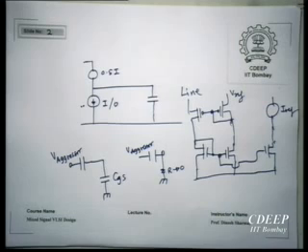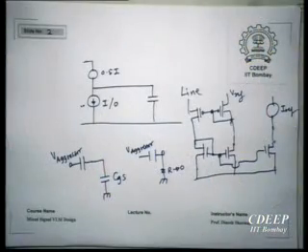The switching wires, the aggressor itself, is not switching by a large voltage. The nearby wire is not switching by a large voltage. So it is essentially being kept within some small delta V. So even this V aggressor is now much smaller. As a result, the overall noise in your system is way below what it would be in the voltage mode, even with reduced swing.